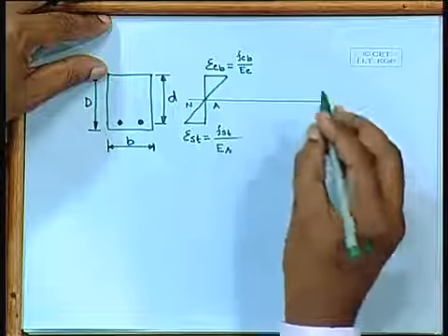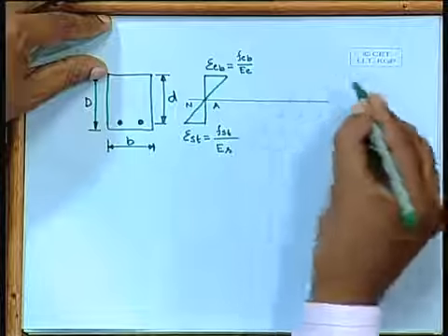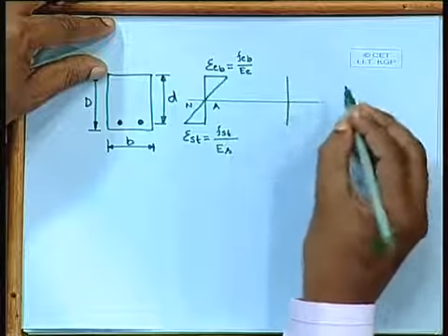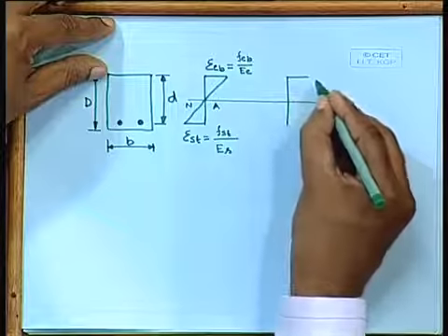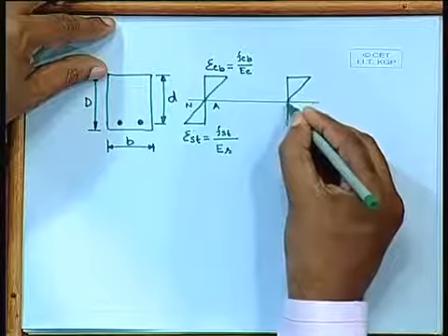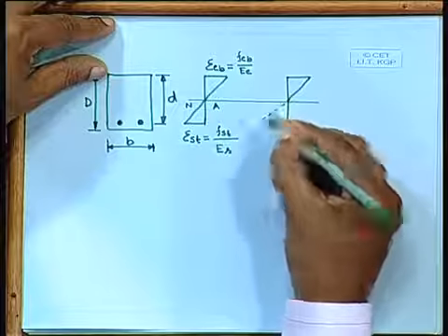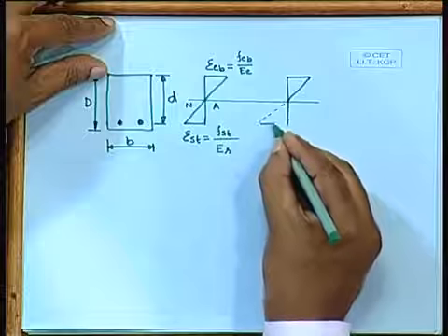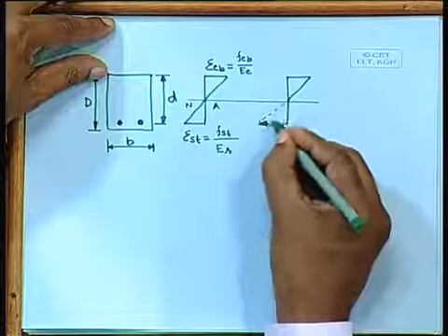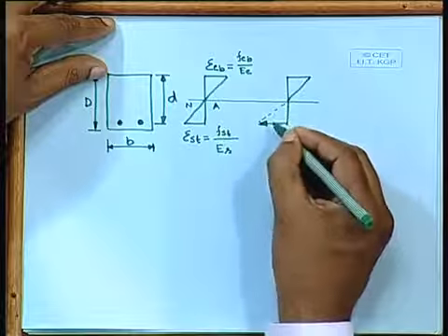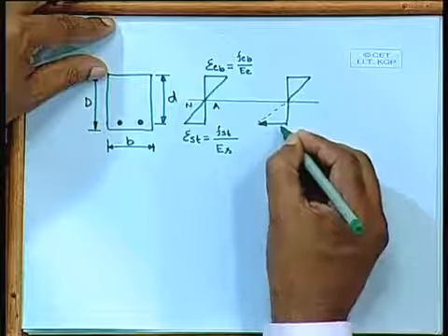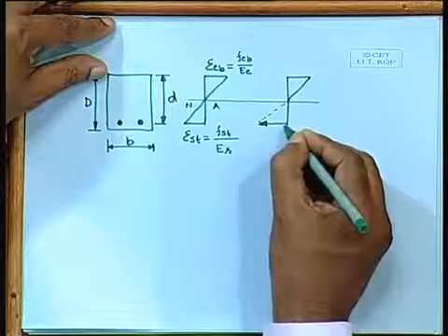We should have the corresponding stress diagram, but since concrete does not take any tension, I am not drawing the stress diagram there, because all the tensile forces will be taken care of by the steel only.